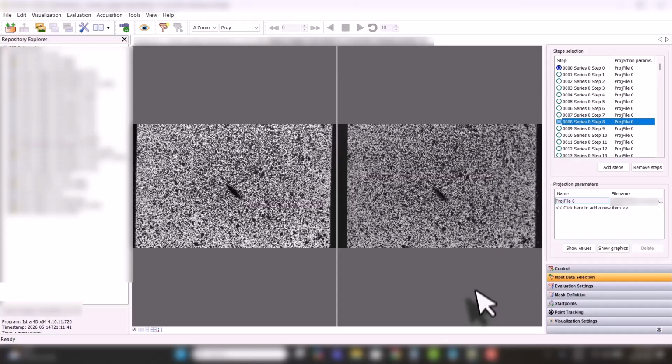So first of all, remember that within a general DIC image series, you're going to have one main reference step. And in most practical cases, that's just going to be the first image in the image series, step 0. Now, yes, you could acquire a series of images and maybe in the first 50 images something is obstructing the view, and the quality images for DIC didn't start until the 50th image, let's say. Well, in that case, you're going to delete the first 49 images and make the very first step the reference step, and it's just going to renumber.